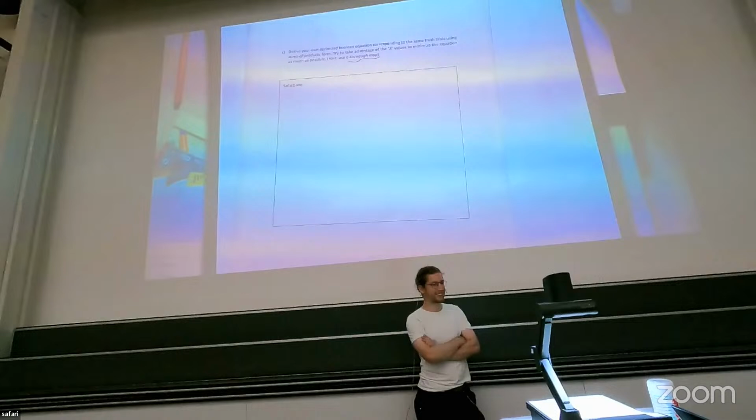So one thing to realize is if you have a question that has only 3 literals, A, B, and C, you can actually just write the truth table, and from the truth table you can work your way out. That's once you realize what's the easiest thing. If you don't see it immediately, you can say, hey, there are only 8 different things that can happen here. You can quickly fill out the truth table. Once you fill it out, you can then do the optimizations like you do on a standard Karnaugh map. So that's sometimes what I do. Not very sure how well it would work there.